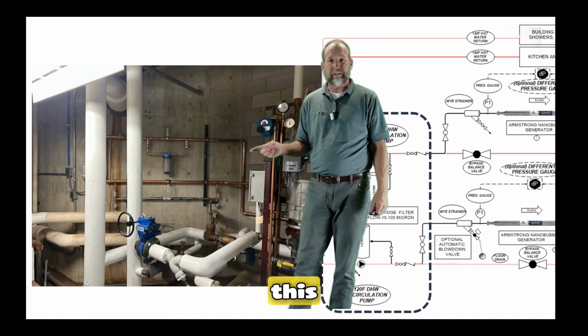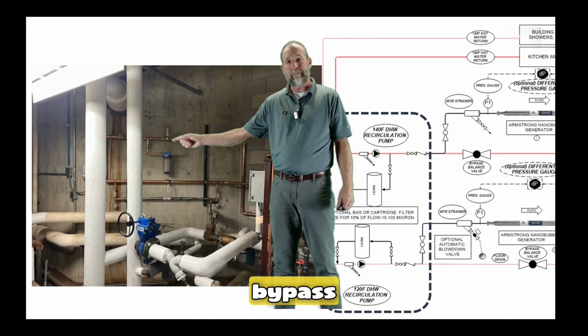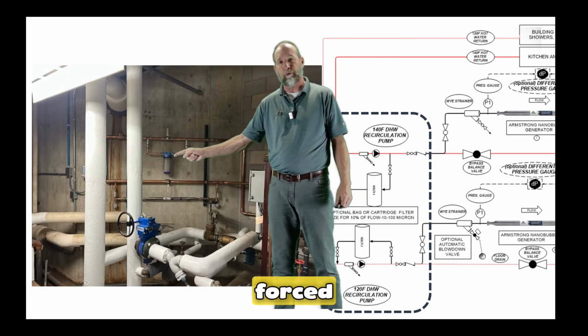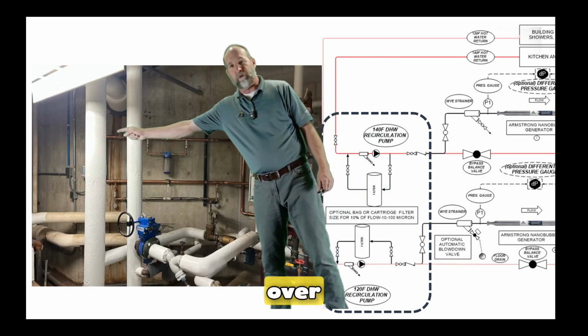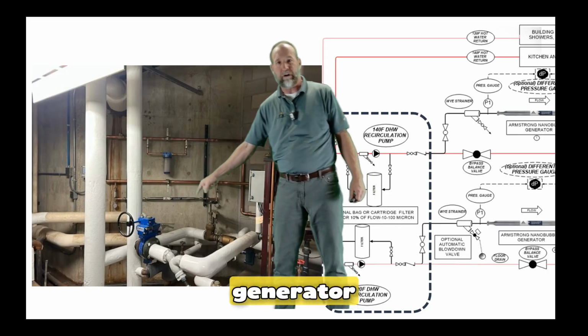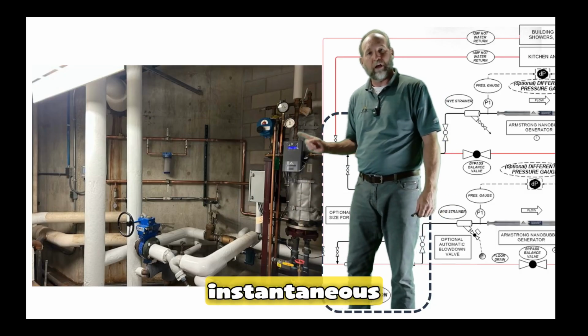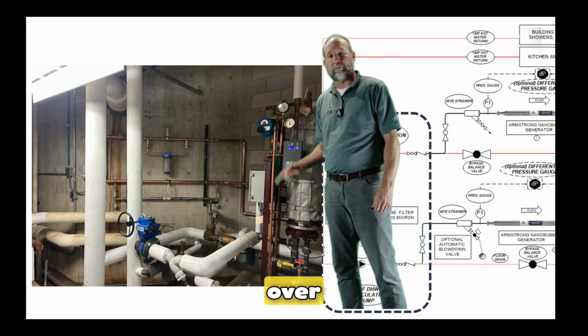But essentially the way that this one here works is that the water flows this way, comes through here. You've got a bypass valve that's closed, so all the water is forced through the filter, goes over here, down, and comes through our nanobubble generator. Down here's our nanobubble generator, and then it goes back to our water heater. We've got a semi-instantaneous vertical water heater over here.